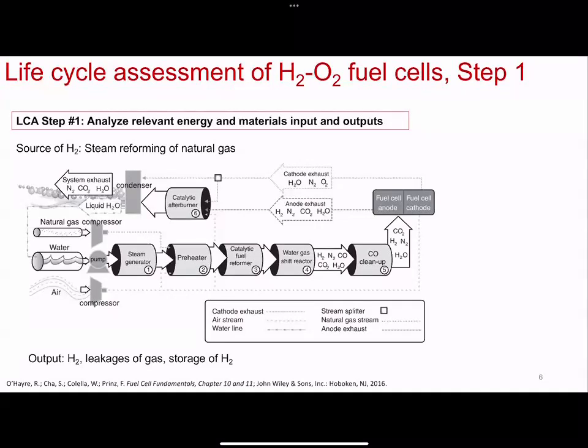So we talked very briefly about steam reforming. That means you inject H2O in the gaseous phase, and it will react and produce carbon monoxide and hydrogen. And then you can do the water gas shift reaction to convert the CO into CO2 and produce more hydrogen. So basically, it can be this cascade of reactions.